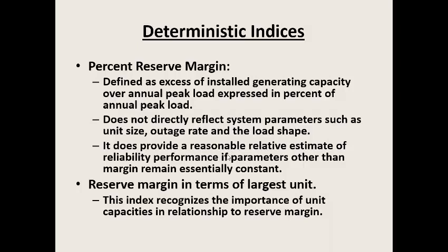So sometimes what is done is that people will try to establish the percentages based on the probabilistic analysis, and then they can use those percentages for some time, and then again they will come back and try to establish the percentages again through the probabilistic analysis. The other is the reserve margin in terms of the largest unit.